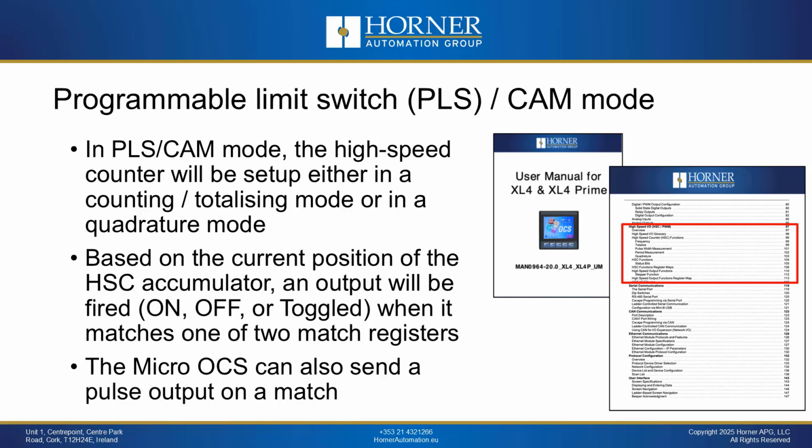It is in the totalization mode, where it is just counting pulses from a sensor, and based on a particular position or a particular value of the high-speed counter accumulator, we are going to fire an output independent of that logic scan. So we do not have to be at the bottom of the logic scan to fire that output. We can do it at any time because the high-speed circuitry on the OCS, not the logic or the scan engine of the OCS, is controlling that output.